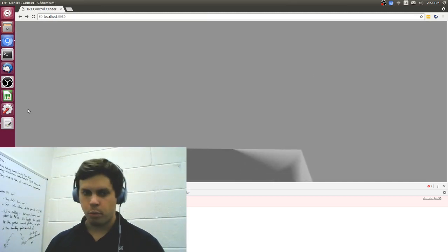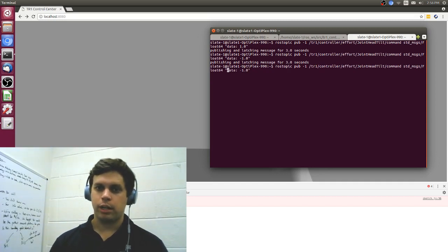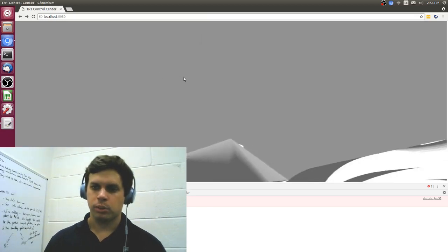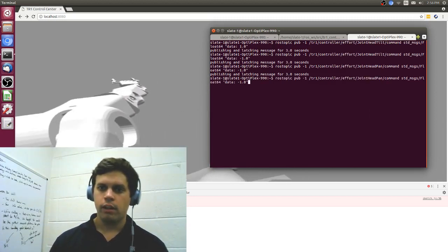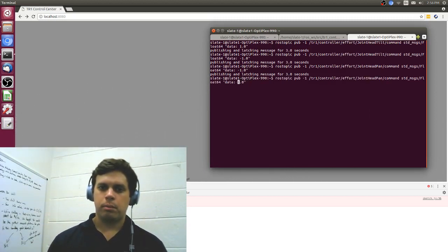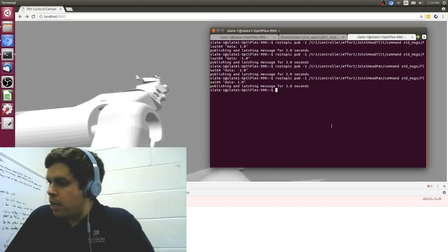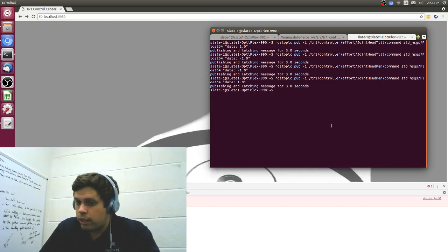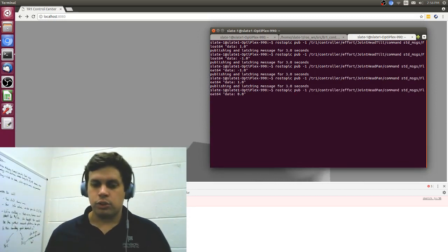There we go. If we go to rostopic pub, instead we publish to the head pan ROS topic, we will see that it turns all the way to the right. And if we do +1, we'll see that it goes around the other way. So we can see already how this is working and how this is actually not going to be too difficult to start to build out.